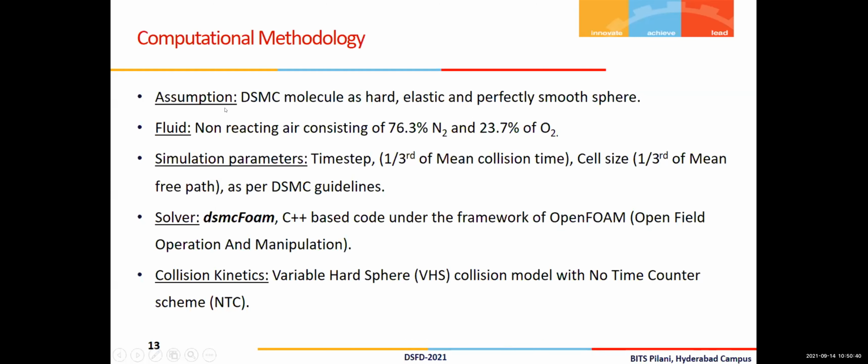Some basic assumptions: we assume that molecules are hard, elastic, perfectly smooth spheres. We have considered non-reacting air, and the time step and cell size as per the DSMC guidelines. We have used dsmcFoam, a solver from OpenFOAM, and we have modeled the particles with the variable hard sphere, or VHS, collision model to compute the interparticle collisions.